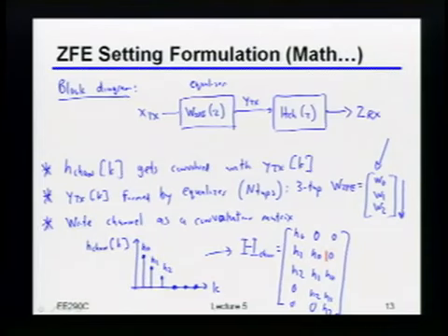So, just in case you're confused, the reason this ended up being 5 by 3 is that this 3 over here is how long my equalizer is. And the 5 is related to the fact that I have 3 responses or 3 taps that I'm keeping in the channel, and these extra 2 are because I have to convolve it with something that has a length of 3. Okay? So in other words, this dimension here is always the number of taps in my channel plus the number of taps in my equalizer minus 1. Okay? And again, trying this on an example makes things much more clear than just hearing me say it. Okay? So everybody comfortable with this?